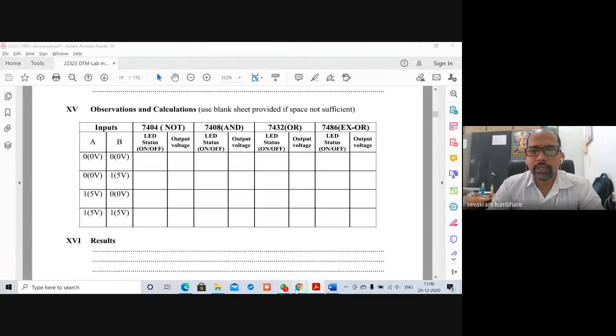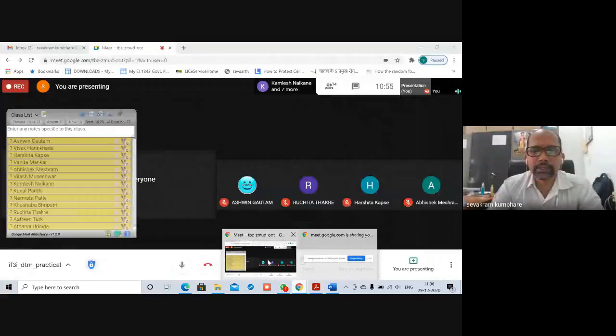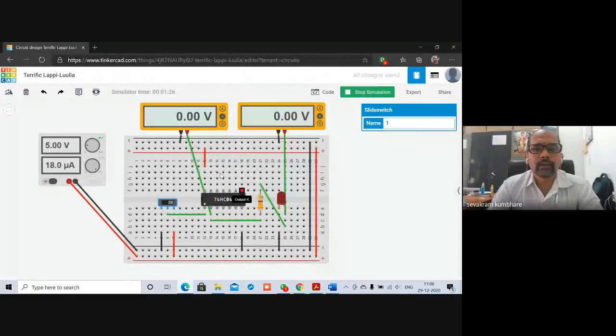So one thing I would like to tell you is this. Now one thing you have to observe, if I make it 0, what happened? Here I am getting 4.64 volt. After that, current is flowing through the resistor and it is coming to this LED input, the anode. But if you observe, voltage at this point is 4.64 volt and voltage at this point is 1.96 volt.